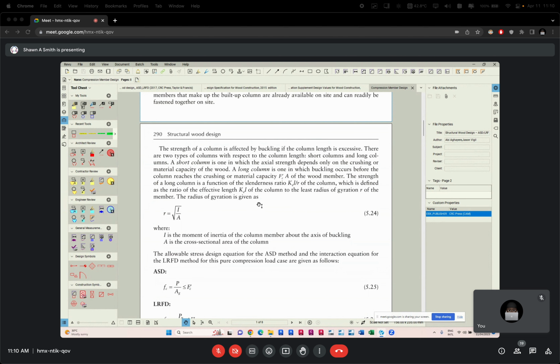However, if you have a rectangular cross-section column, one axis is going to be stronger than the other. We check the weak axis, unless, of course, we have some internal bracing in the weak axis, which can cause that axis not to be weaker than the original weak axis. So it depends on the geometry which you are given. But just remember, we have to check slenderness.